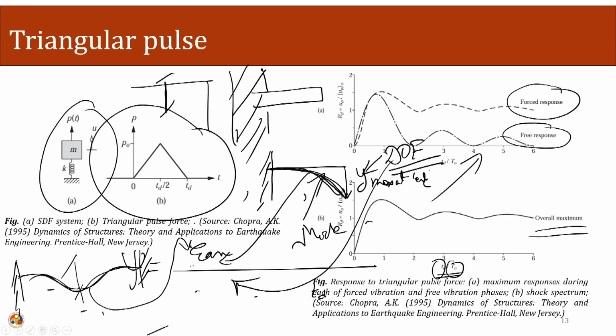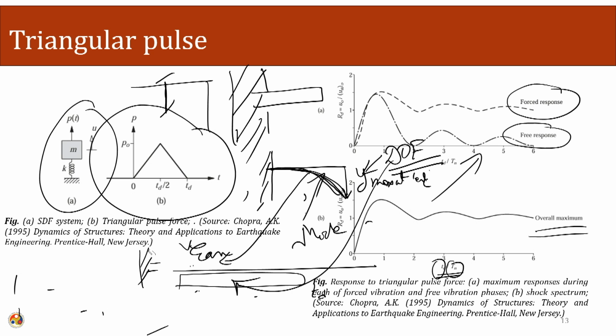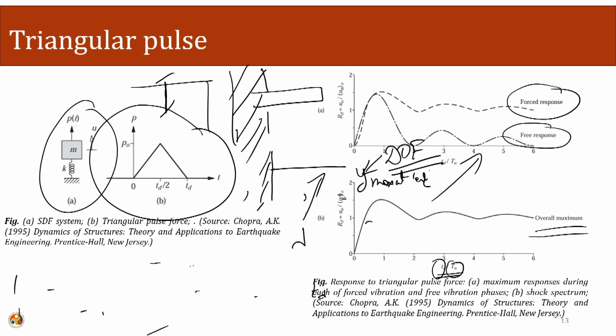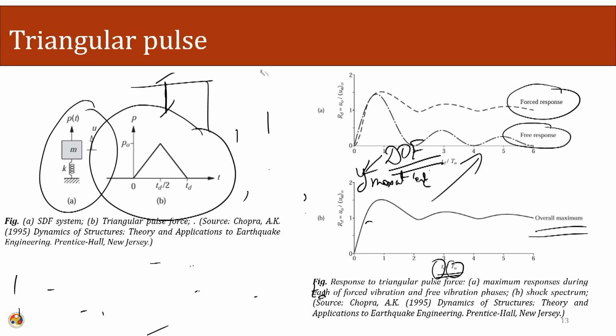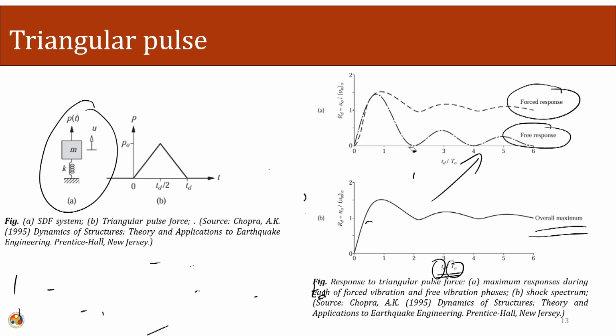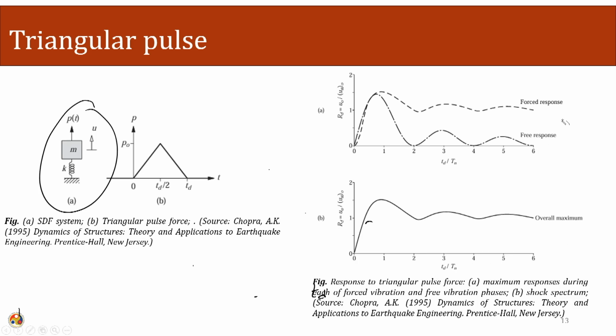Similarly, we can choose our degree of freedom wherever we want, and that will be reflected in the denominator. In this way we can choose the required degree of freedom and the required mode shape. The effect of the required degree of freedom will be shown in the denominator, and the effect of the required mode shape will be shown in the numerator. Using this equation of the shape function, we can choose any degree of freedom and any shape function required.